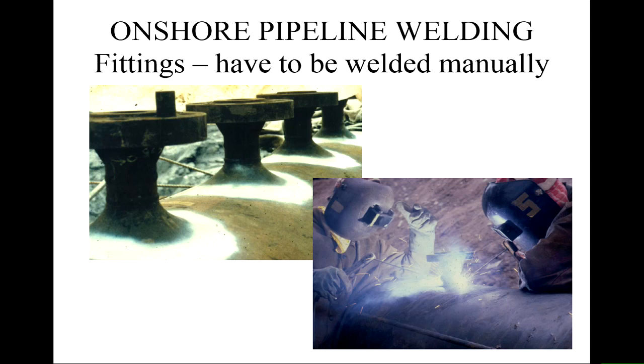Most fittings have to be welded manually. I would say all fittings, but I did mention under the fittings cold bends in the field, and those can be done in an automatic way if the bending is not too big. Anything which is a tapping point, a port, a T-piece, it's done manually. So these are manual welds, and you might ask, well, why is this all painted white? Well, this has been painted white because it's been dye penetrant inspected. So this is one of the stages of the inspection process to see that those manual welds are good.